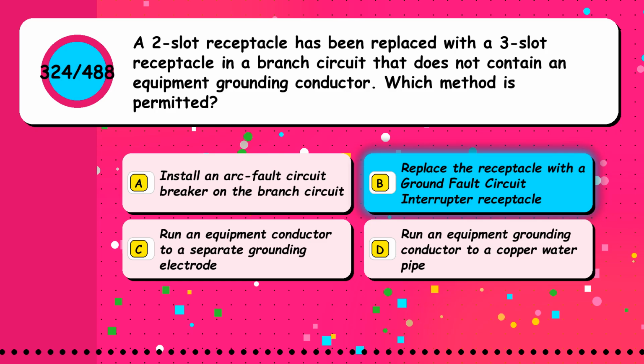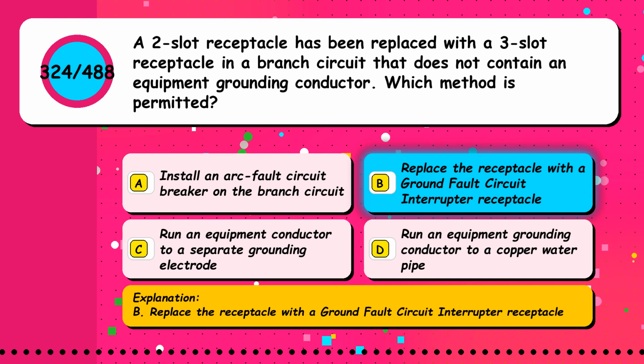The correct answer is option B. Replace the receptacle with a ground fault circuit interrupter receptacle.